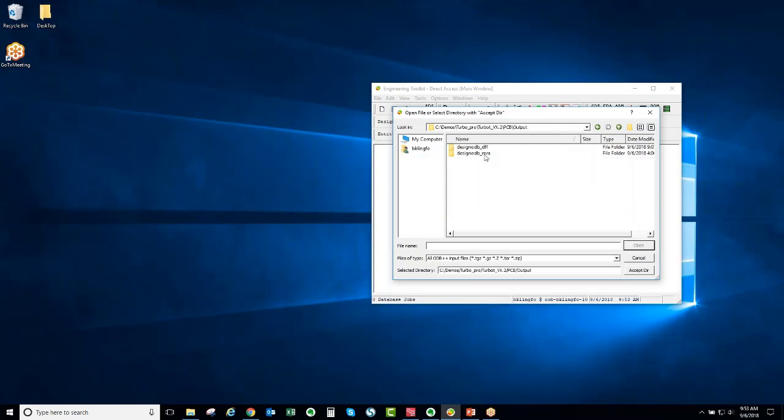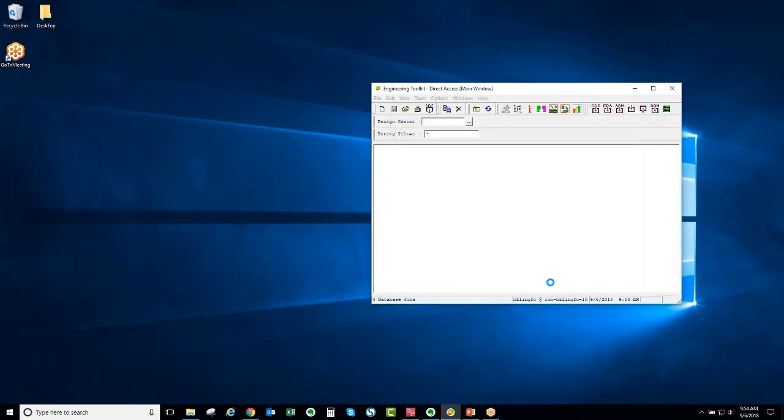And this is a folder structure basically for ODB++, but you can open the standard TGZ file that most tools produce for ODB++. Go ahead and accept that directory. This will then bring that data into the Valor NPI tool. Now at this point in time, I can go through and I can manually continue to look at this data.